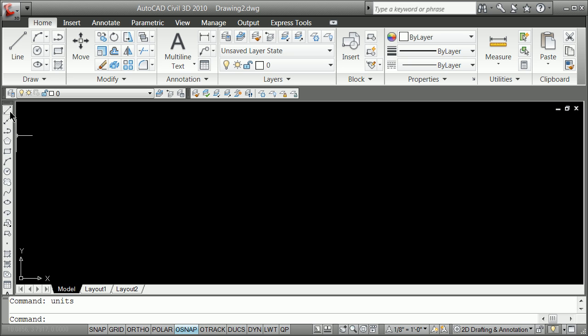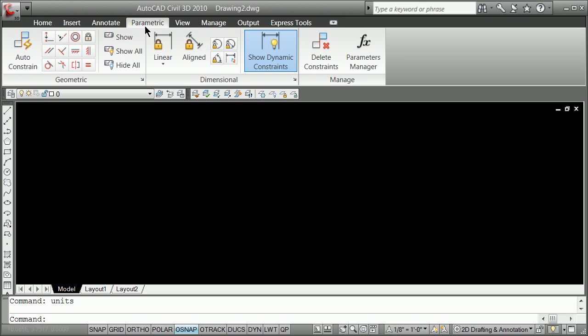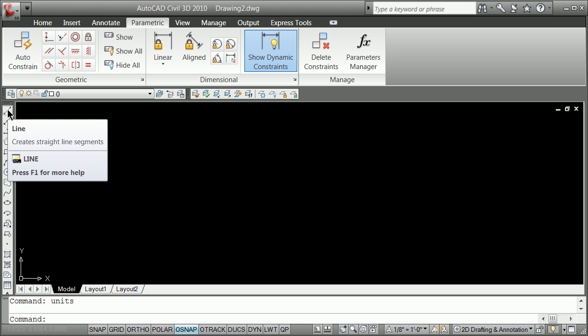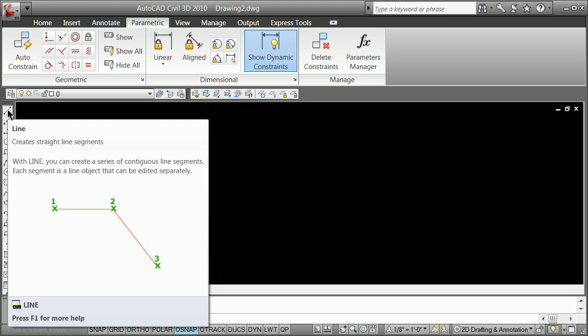I'm going to show you now the basics of using parametric, and it turns things on their ear. This is an important shift to make, not only for Civil 3D, at least in your head, but Inventor, SolidWorks, and eventually anything that's going to be parametric modeled. They say the key to doing parametric modeling is to sketch in the shape of the sketch, and that would generally be to put lines where there are lines, arcs where there are arcs, and have the right number of vertices in the drawing, and then back in your description of your parameters.